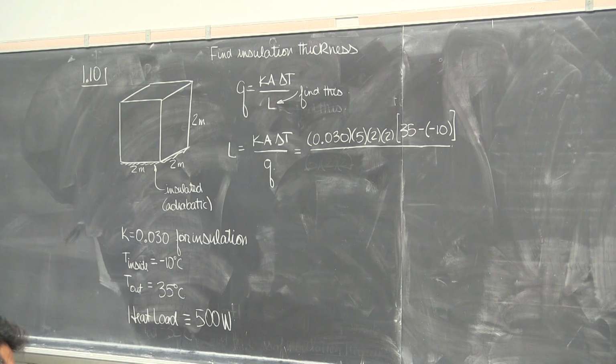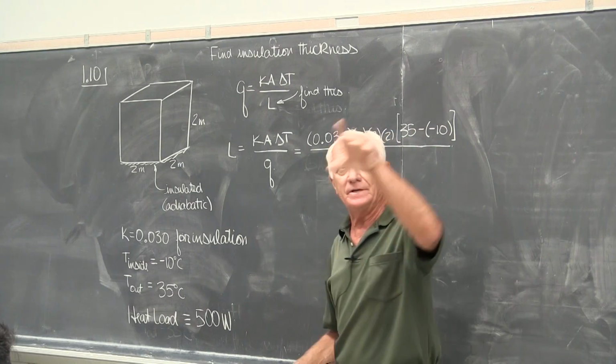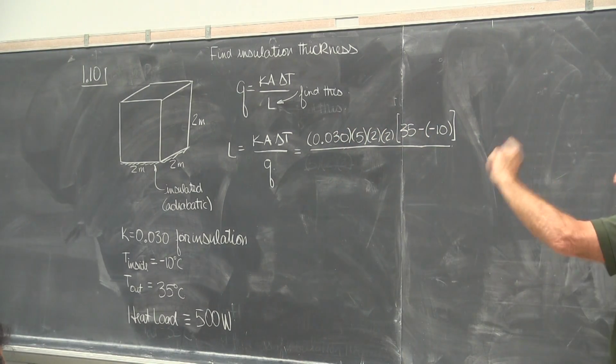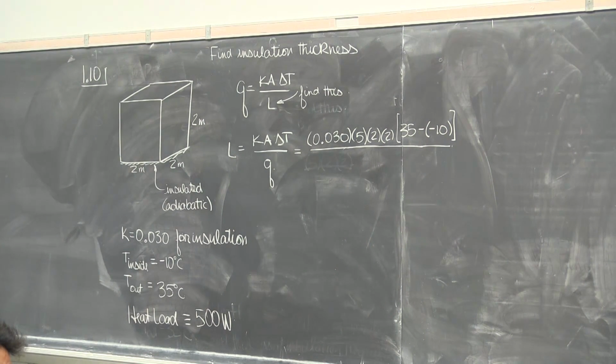Pretty much the hall in here is the same temperature. The room over there is the same temperature as here. The room over here is the same temperature. So the heat comes from the outside if it's a hot day. You add all that together. That's the heat load. That means that HVAC system has to take out the heat from our bodies, from the lights, from the PCs, in order to keep the temperature in here from changing. Otherwise, this room gets hotter and hotter.